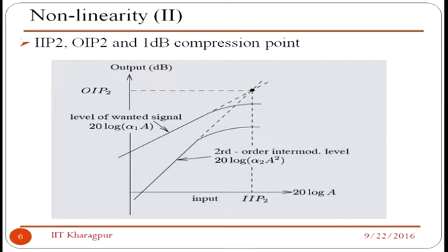You know that today it is an accepted topology. If you want to design a transmitter, you go for zero IF, and if you want to design a receiver, you go for low IF. That's a thumb rule accepted by the RF community. Because if you go for super heterodyne kind of structures, it will give you more hardware count. You will have 2 or 3 mixing stages and filters.